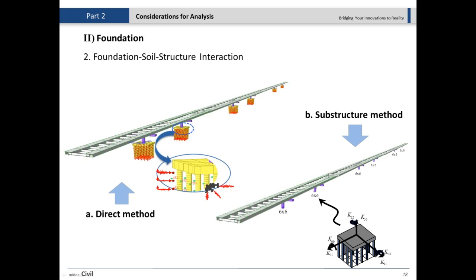Okay, but there are also a couple of things that we should do. For example, assume that you have 50 of these micropiles here, and you have to simulate each pile, let's say 20 feet, 30 feet, or 50 feet deep, experiencing different layers of soil. So definitely you need to apply different springs at each point, because they don't have the same spring response.